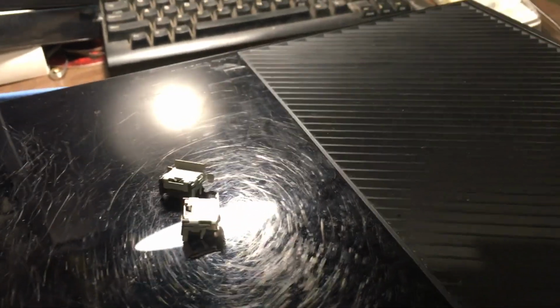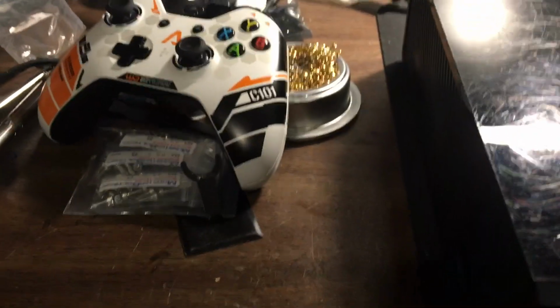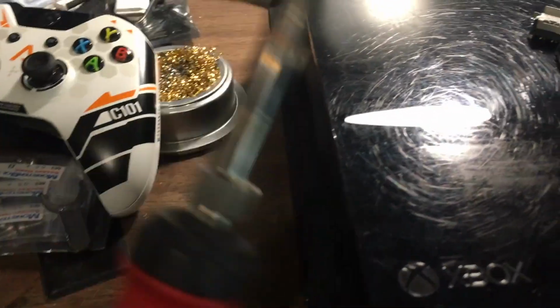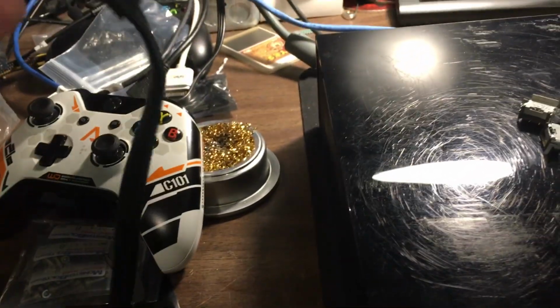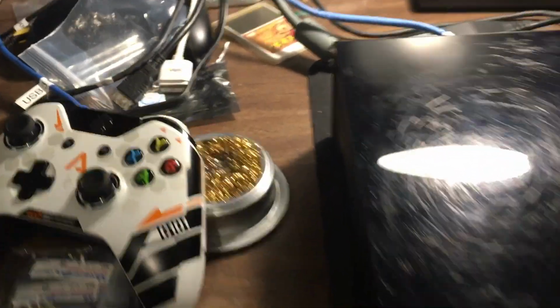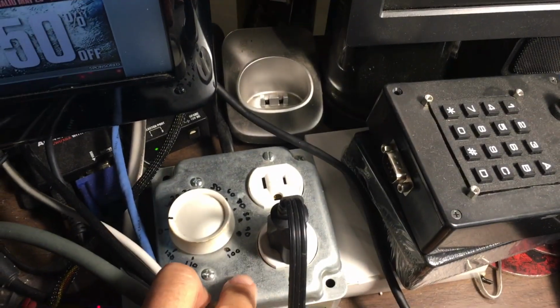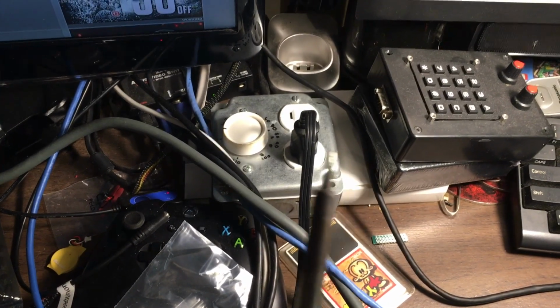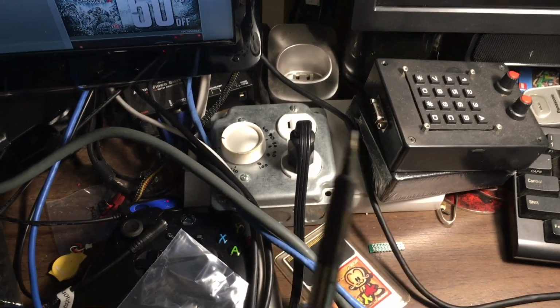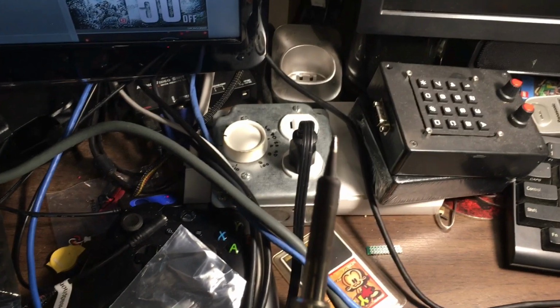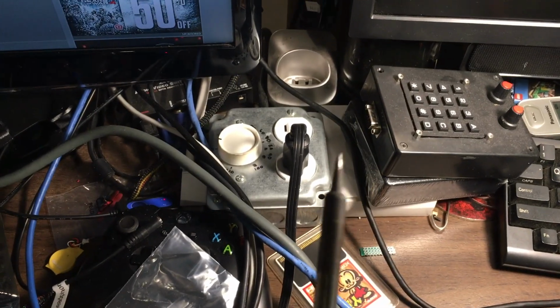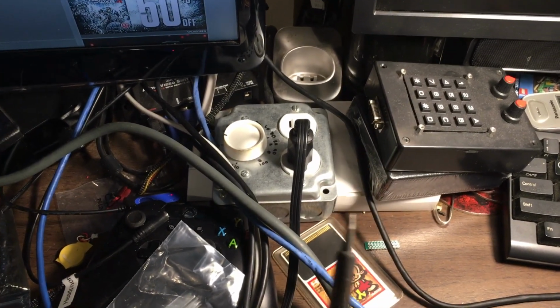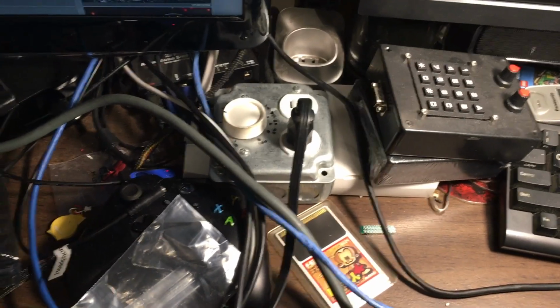I haven't actually done this before, and I have kind of a crappy setup here. I have a soldering iron that's a direct plug, where I don't have a lot of control over the temperature. I do have it hooked up to a dimmer where I can control the voltage. But this particular iron gets really hot. It gets over 1,000 degrees Fahrenheit, but typically you want to run it between 500 to 600 degrees Fahrenheit. That's about the melting point of most solder, particularly leaded solder.